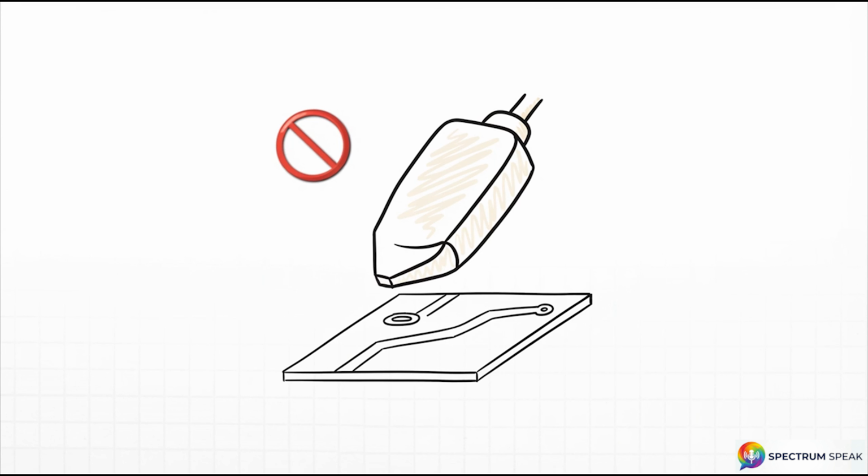Think about it. If you try to measure a high-frequency switching node by physically touching it with a standard passive 10x voltage probe, you instantly inject several picofarads of parasitic capacitance right into that node. At high frequencies, that capacitive loading hits the circuit like a sledgehammer. It artificially drops the resonant frequency, dampens the voltage overshoot, and basically masks the exact physical behavior you're trying to diagnose. Non-contact near-field probes are the workaround here.